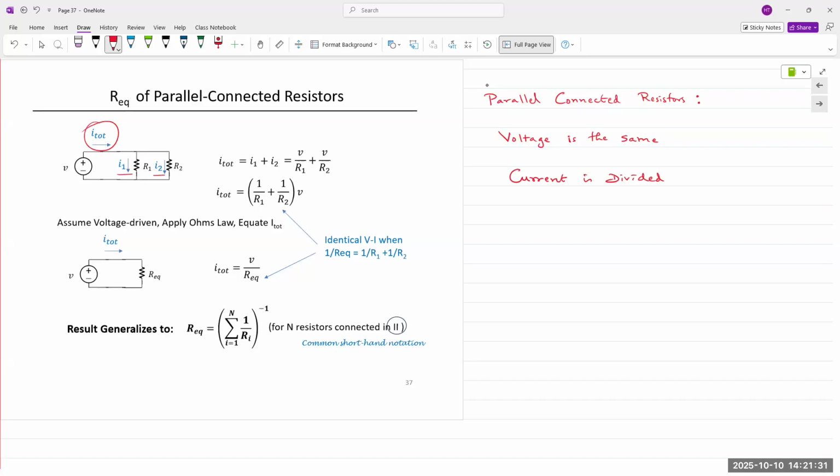This is simply showing the derivation for Req. And another technique we can derive for this is the current division principle. These are all derived from Ohm's law. They're simply shortcuts. Okay, they're shortcuts that allow us to quickly determine the voltage or current through any particular resistance.